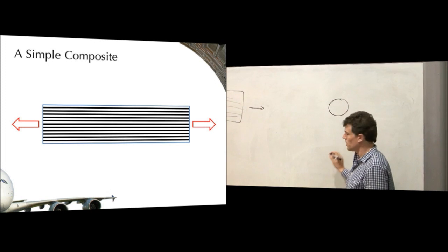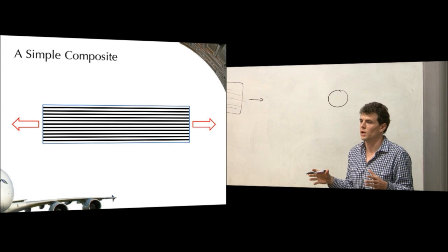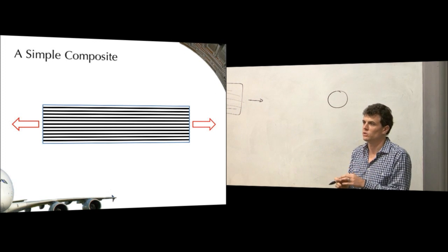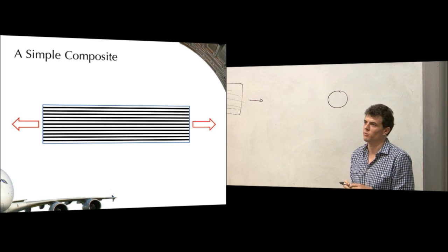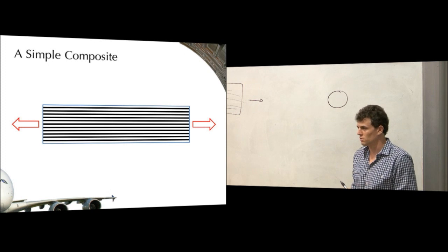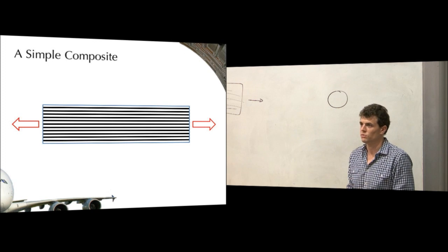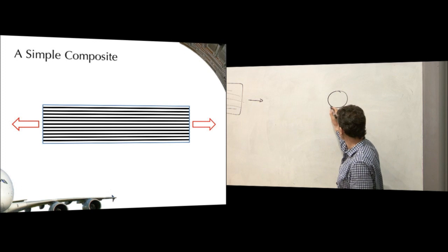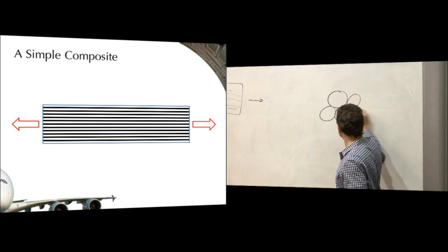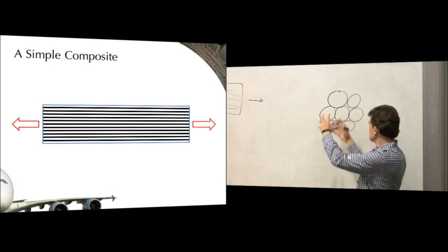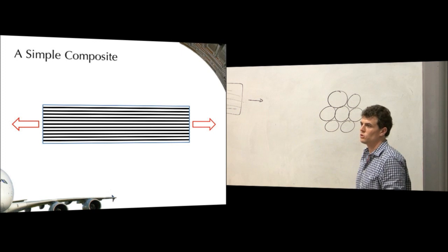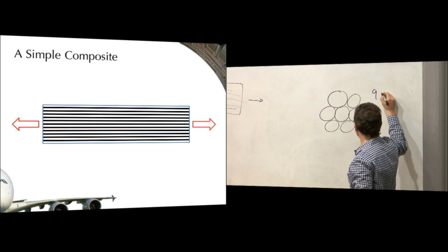Well, if we think about how if you put ping pong balls in a container, they can't fill the container because they're spheres, there's gaps between them, and you can work out the most efficient way of packing balls into a container. It turns out that atoms in a metallic lattice are often packed in the most efficient form that they can be. Now, the way you can work out how densely packed you can pack fibres in is to imagine that they're packed in a hexagonal shape. They're cylinders, so they're coming out of the board as tubes. But it turns out that the maximum is about 91%.